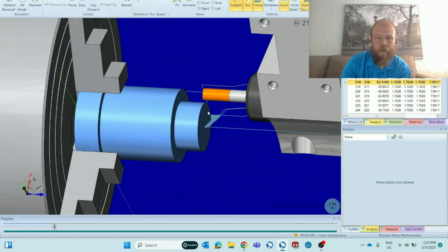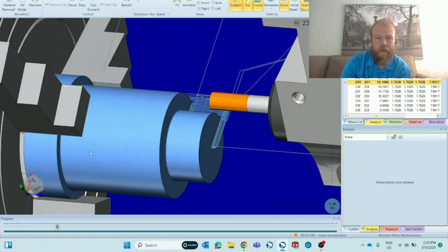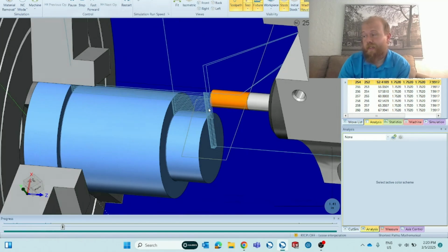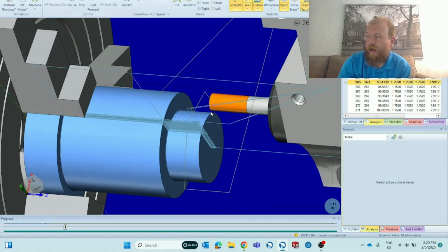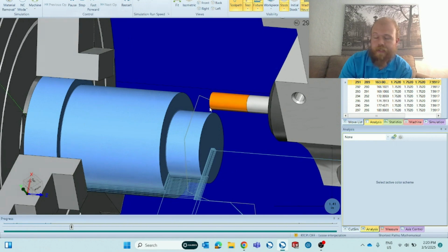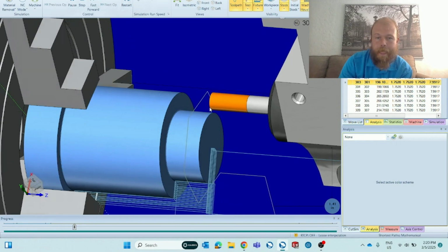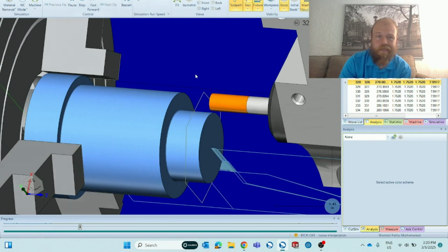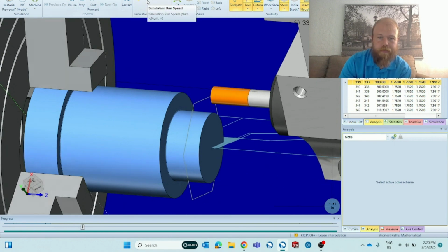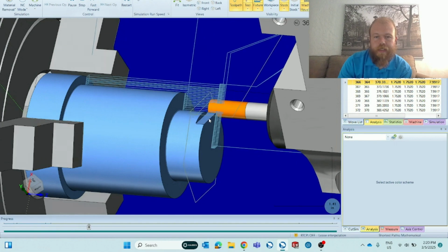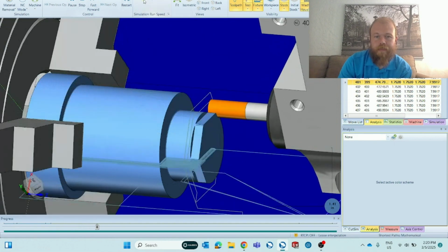Here comes the milling tool, coming down in X. Now I've already turned down this stock, so there's some air cutting still. I would want to eliminate that first pass that I did with the side roughing to eliminate this air cutting of this pass around here. It's actually going to do 4 of them, I believe. Oh, there we go. So then it goes in and does the roughing.